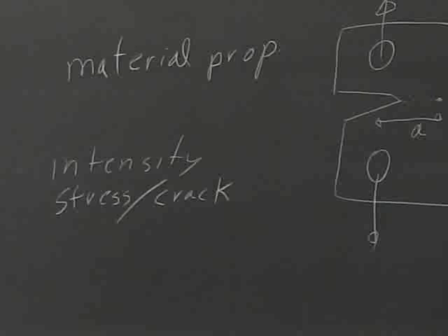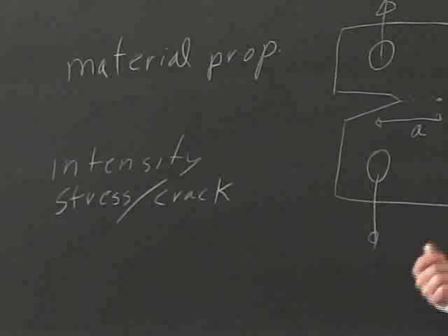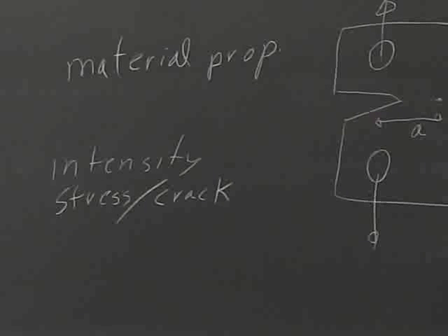And that's why sometimes we do see so-called striations on the fracture surface. Not always, but a striation is because you open and close, you open and close. And you're going to go faster if you have a high intensity of closing, a high range. That's why it's a question of range here as opposed to maximum value.